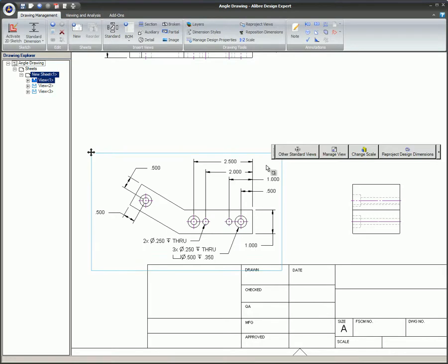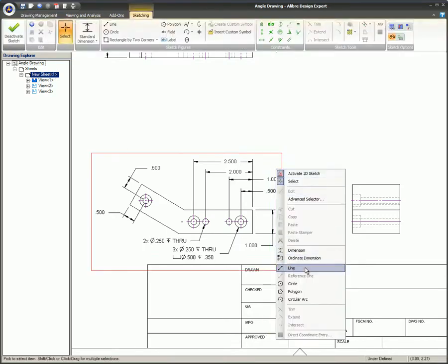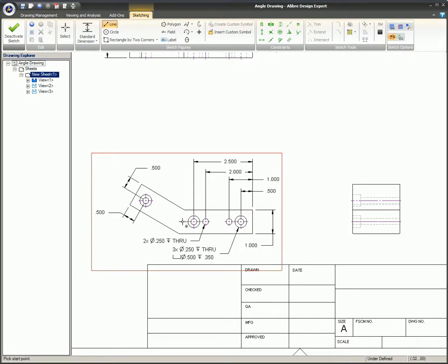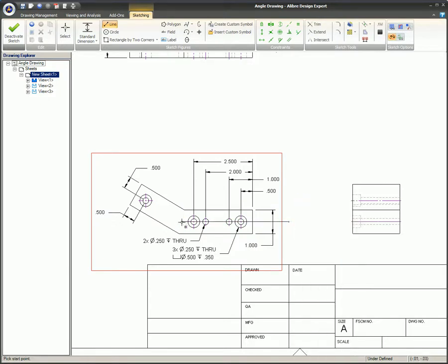Click on a view to select it. There will be a blue bounding box around the view. Sketch a line or a series of continuous lines on the view that go through the part. The lines can be sketched outside of the bounding box. When this happens, the bounding box will automatically enlarge to encompass the entire sketch figure. This line will be referred to as your section line.